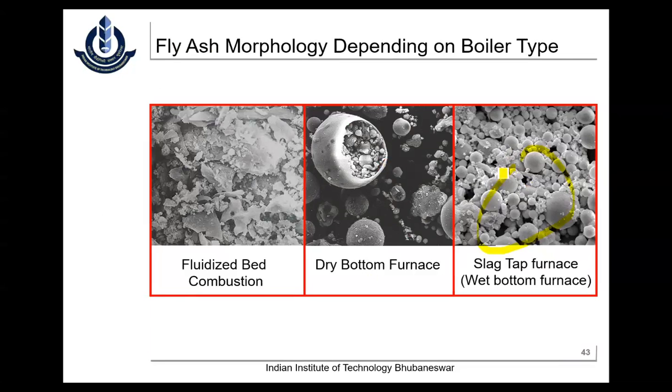Like some of the applications, we're developing mixed designs for high-end applications, and they're literally using fly ash for making self-compacting concrete. It's a wonderful material for highly flowable concrete. If somebody asks for self-compacting concrete, please go and use this fly ash along with some metakaolin. In fact, there was one question, sir: whether fly ash can be used for self-compacting concrete. In fact, you have answered the question now.